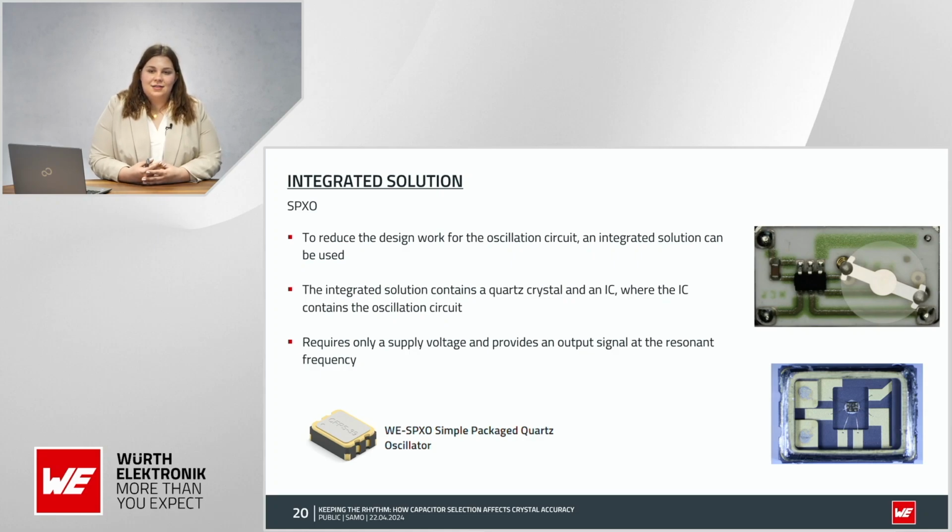A clock oscillator, you could say, is the integrated version of a crystal, because we still have the crystal and we have an IC inside the package that contains the whole oscillation circuit. So the whole Pierce oscillation circuit, the capacitors and everything, is already built into this component.